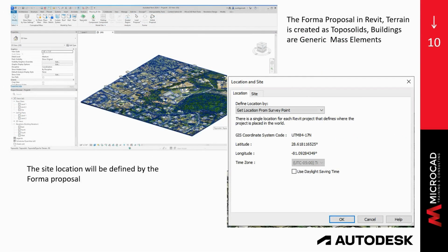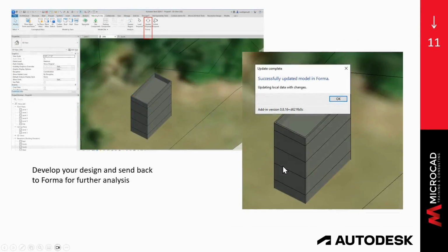Now, in Revit, you can go ahead and start taking a look at the site, right? You're going to prepare your views and all that stuff and start creating something basic, right? It could be your early design stage. For that, we typically recommend making use of your mass and insight tools, right? So show the masses, place basic constructions, right? In this example, as you can see, it's a simple building, just super simplistic, a couple of walls, floors, right?